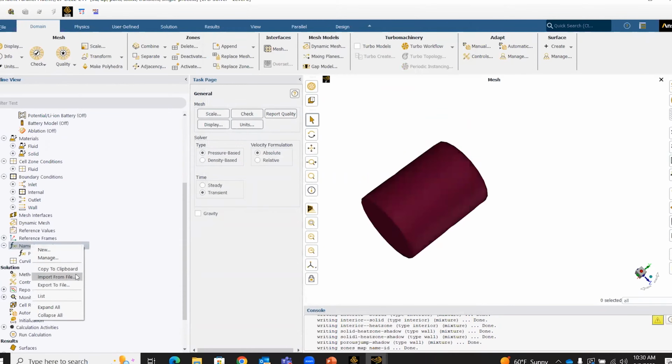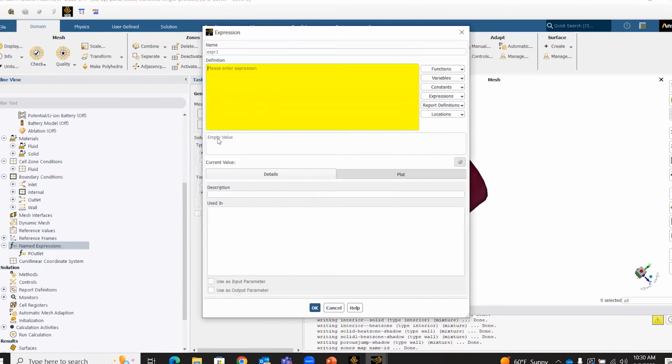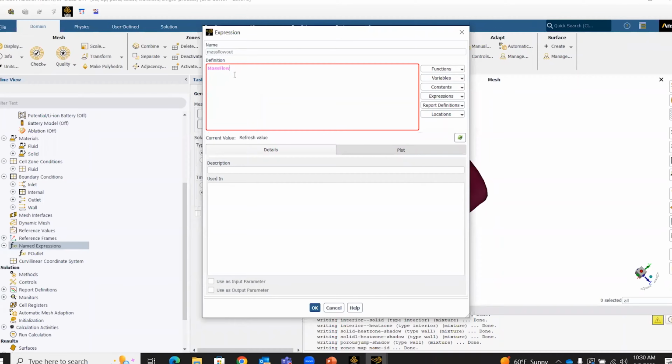I also get the mass flow rate at the outlet. So let me go ahead and enter another expression over here. And as soon as I click on M, it'll give me a bunch of options to choose from. Okay, so I could go with mass flow, or if I was writing some other kind of expression, maybe I'm going to use a reduction or an averaging function, then I could also go with mass flow average. But in this case, I'm simply going to choose mass flow.